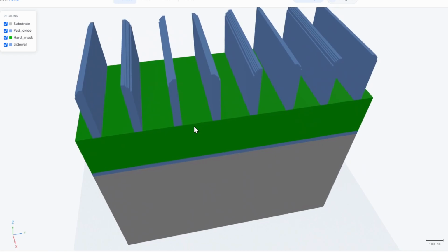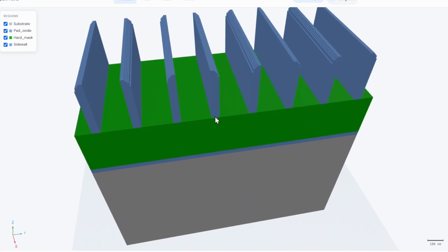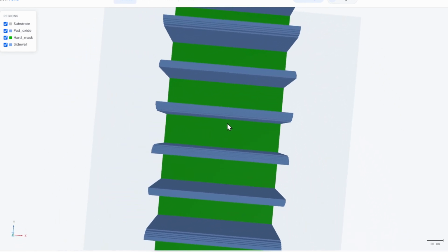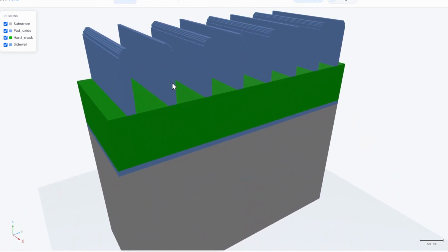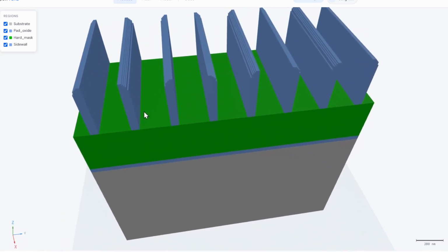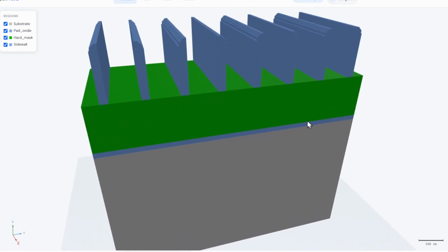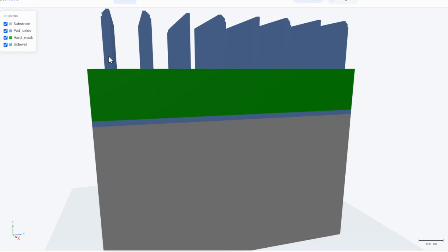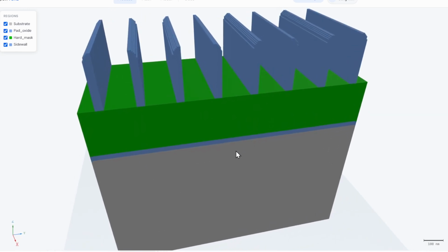So they are separated by a certain distance, but the point is their width is determined by the deposition depth, 7 nanometer. They will be the basis of the FinFET. Okay, but please note that this is just silicon dioxide, and actually what we wanted to do is make this thin pattern in the silicon substrate. So how can we do that?